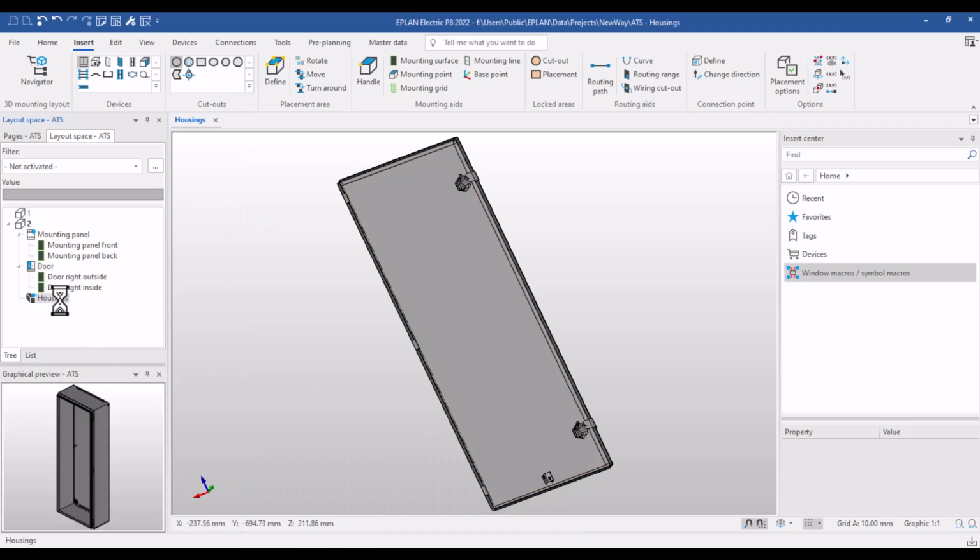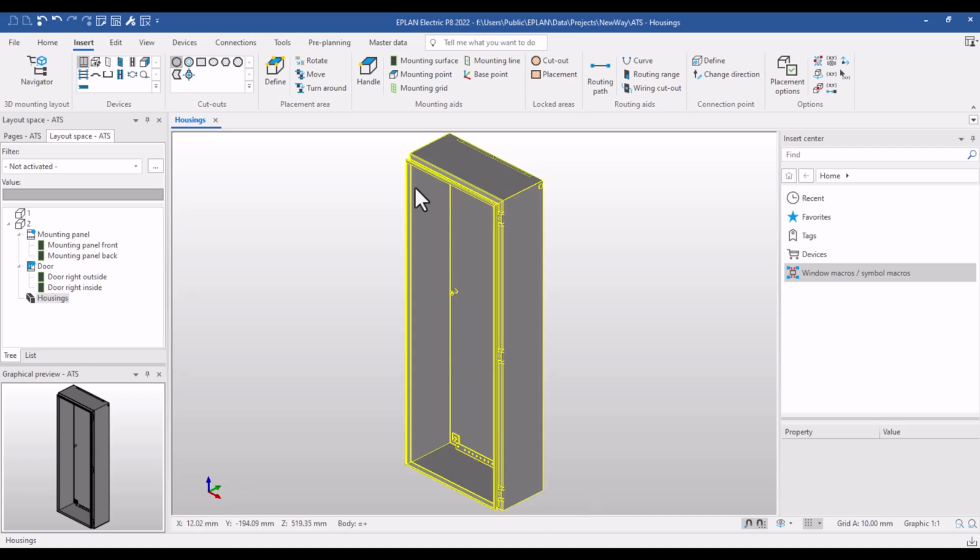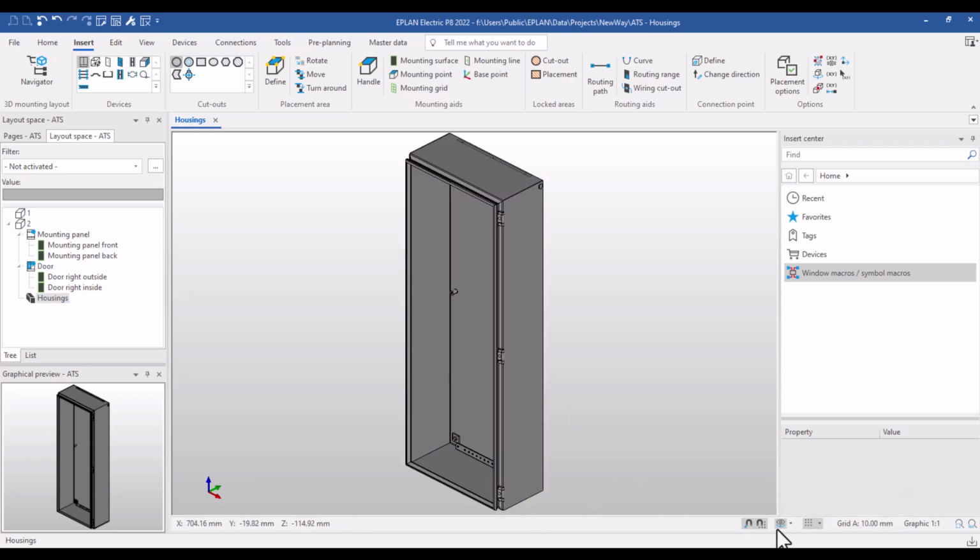After that, if we want to go to the housing, you have several options. Do you want to mount on this right place and left place, or you don't want to place any component in it? If you want to place any component on the right side, you will need to define this place to be a mounting surface by pressing mounting and choosing this place as a place where we can mount a component. Several times we can mount a component on the right place. So let's define it as the mounting surface.